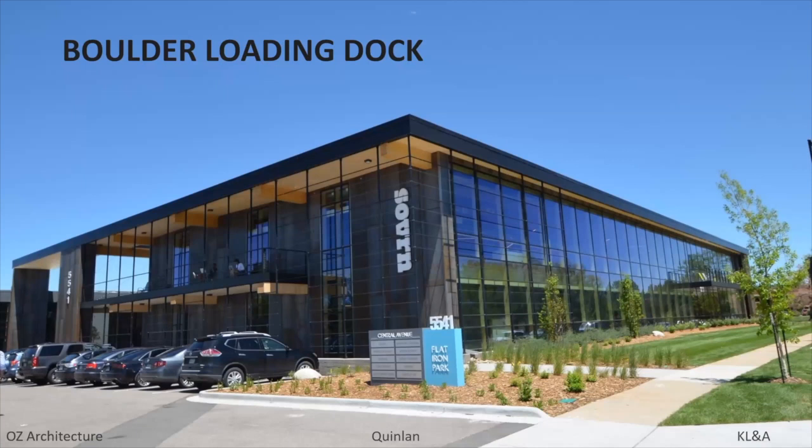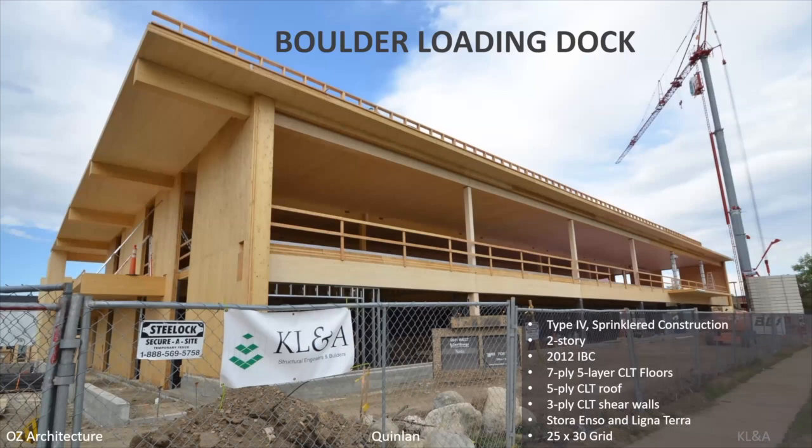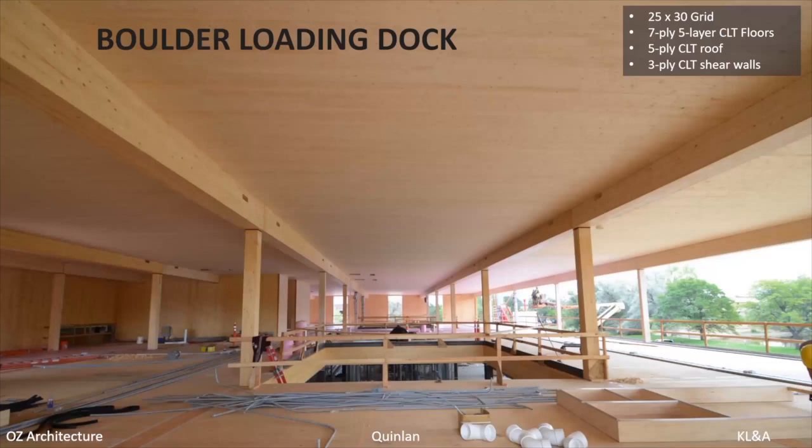Here's a mass timber project that we did in Boulder. It's a 2-story type 4 building. And here we chose to use that post beam plate system. The grid is 25 by 30. The span here is 30 feet. And then the span of the CLT is 25 feet. If you've been paying attention, you know that's a pretty long span and might be a particularly expensive one as well. We ended up really driving the design by owner requirements for openness in this area.